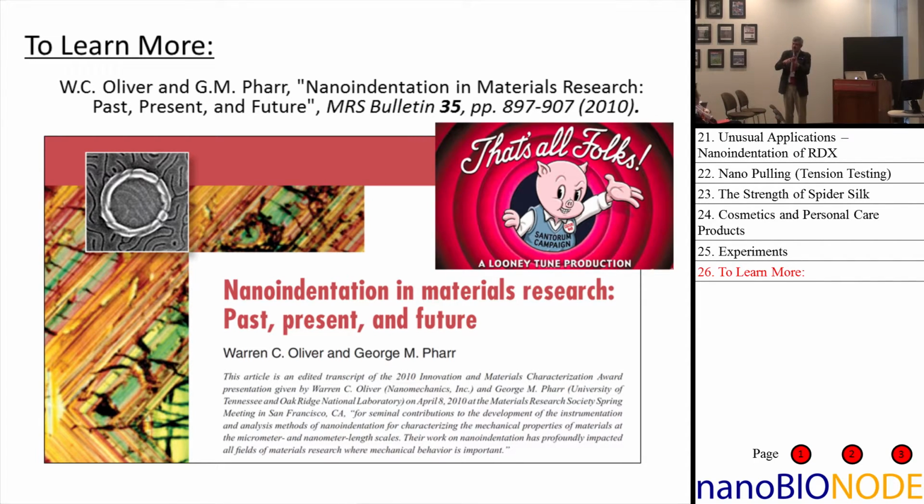The other for me is building in situ systems to work in a dual beam FIB, focused ion beam system, that let us go in and test things and manipulate things that are sub-micron in dimension: pick them up, mount them, test them, push on them, pull on them, bend them, make objects that have small cracks in them.